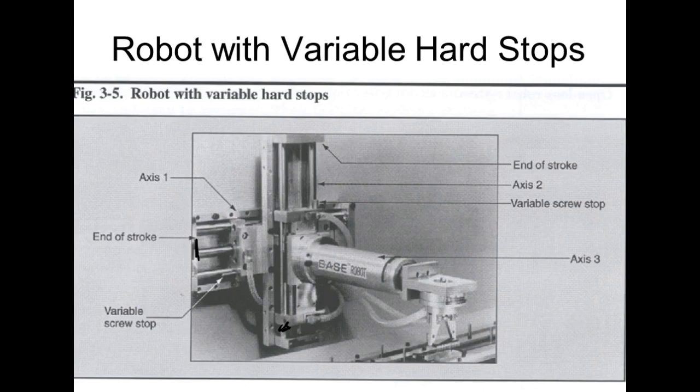Now, what we've done with the FANUC, since it's electric motors, when it hits that hard stop, it energizes the switch, so it cuts off the motors. Because if I stall that electric motor, it would burn up.